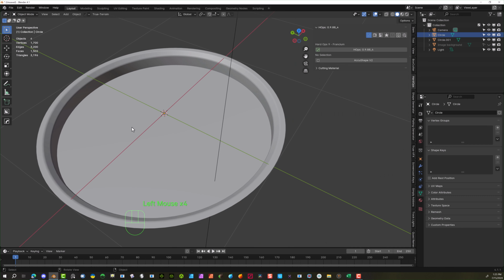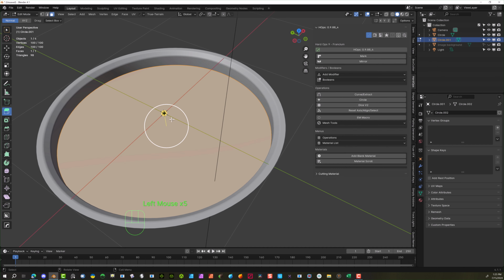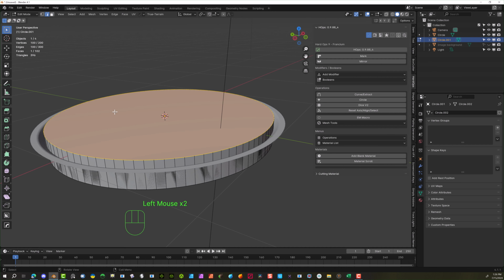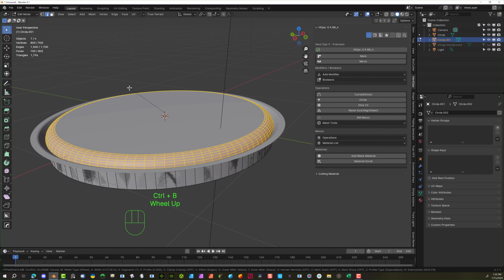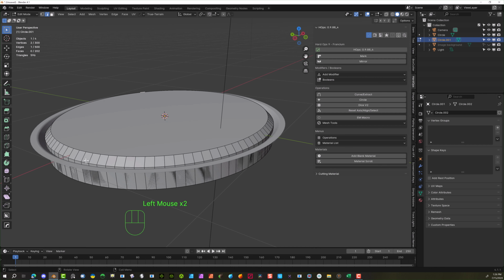We're going to go to edit mode. Here on the face, make sure we select the face tool, select it, and hit the extrude button to bring this upward. Now I'm going to add a bevel to this. I'm going to pull this out with Control B and make that into a chamfer instead of a bevel. With just one cut, it becomes a chamfer. If you have more than one, it becomes a bevel. Alright, that looks good.